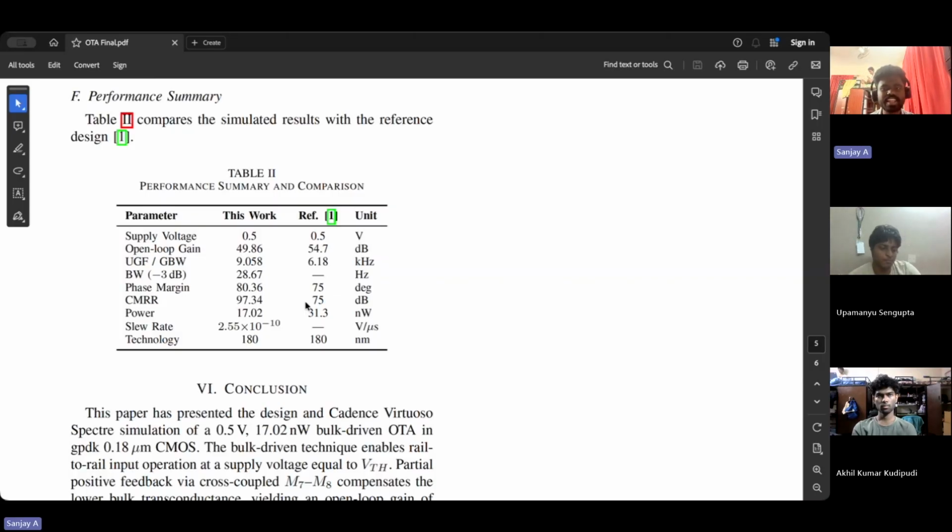For an ECG signal at 5 millivolt amplitude and 150 Hz maximum frequency, the required slew rate is 2 pi times 150 times 0.005, which is approximately 4.7 millivolt per millisecond. We have more than 200 times what we need. Slew rate is simply not a binding constraint in nano power biomedical amplifiers.